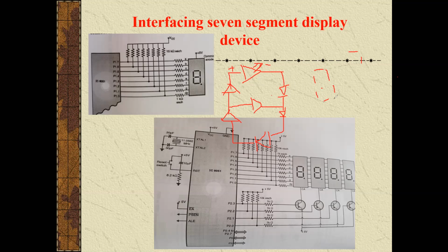In case of common anode connection, for glowing the LED, the current will flow across each LED, and the current should not exceed beyond 2 milliampere. While displaying, the current should flow at a particular LED to make it glow, but the current should not flow beyond 2 milliampere.